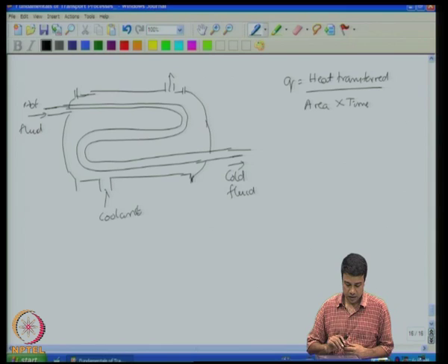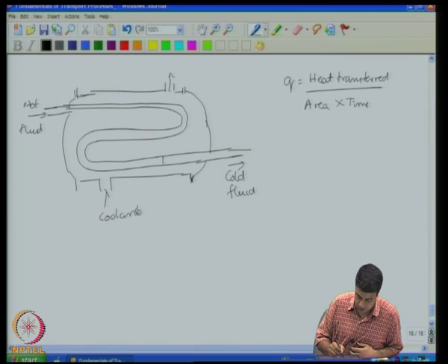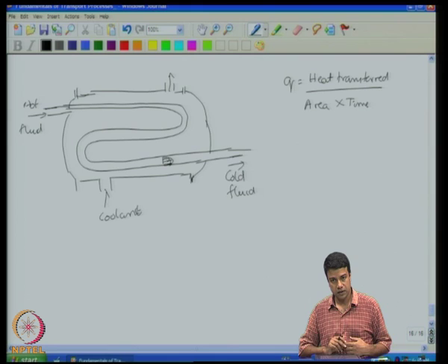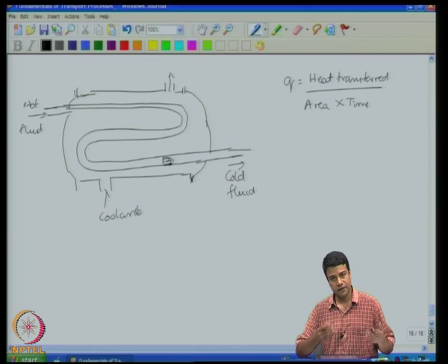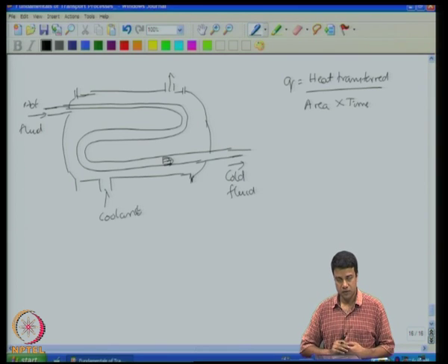In addition, it is not going to depend only upon the mean velocity, it is also going to depend upon the details of how the flow is within the tube of the heat exchanger. If the flow is of a laminar type, you have nice straight streamlines, you will have a lower heat transfer rate. If it is a highly mixed turbulent velocity profile, then the mixing is far more efficient and you will have a different heat transfer rate. So, it is also going to depend upon the fluid flow properties, that is the density, the viscosity and the velocity. So, let us assemble all of these.